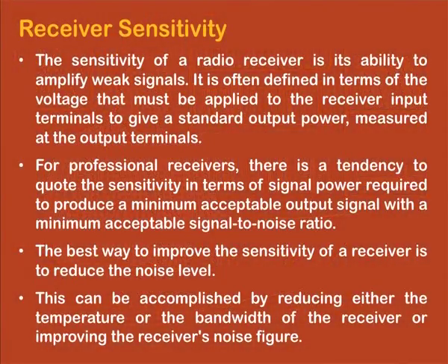The sensitivity of a radio receiver is its ability to amplify weak signals. It is often defined in terms of the voltage that must be applied to the receiver input terminal to give a standard output power measured at the output of the receiver. For professional receivers, there is a tendency to quote sensitivity in terms of the signal power required to produce a minimum acceptable output signal with a minimum acceptable signal to noise ratio.